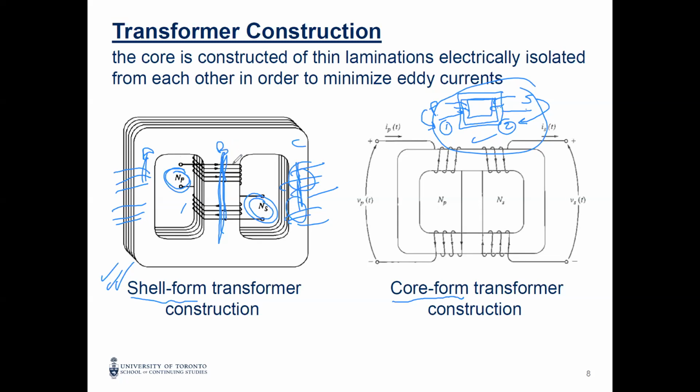They want to reduce the leakage because the flux flows directly from the primary to the secondary, so there is no leakage compared to the one if you put one winding on each leg. So you have some leakage here, leakage there, and then the one in between, but you have more leakage for the core. Here we have less leakage. Okay, all the flux going from the primary is already passing through the secondary.